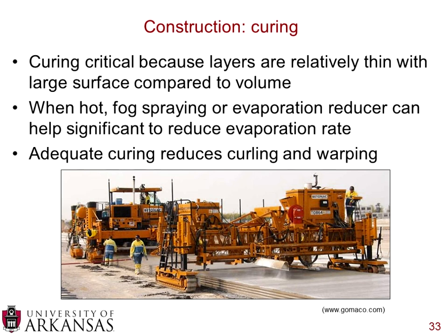After it has been textured, you do want to make sure that it's cured properly. Because these overlays are a little thinner, you have a very large surface area compared to the volume. So just like you want to make sure you have a moist surface underneath, you want to make sure that it's not too dry on top, because you could have excessive curling and warping if that water starts evaporating from the top too quickly.